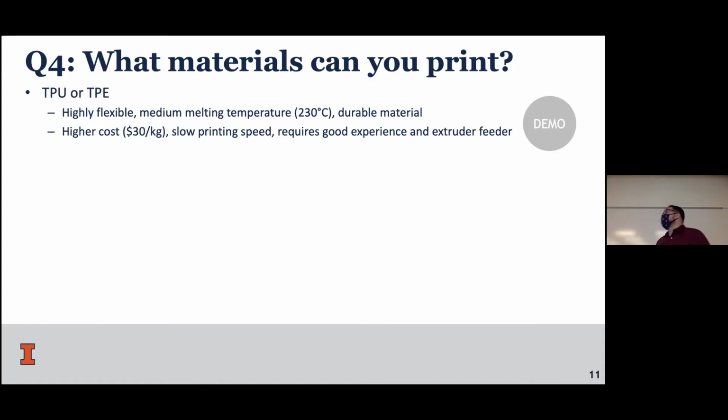Once you've selected a brand, it's usually guaranteeing a certain quality, consistency, homogeneity. But if you really want to buy without looking at the name, you can look at the melting temperature and the density. Usually they give the accuracy of their size. So if you have a printer that doesn't have really good tolerance on filament size, then you might want to change brand for a better filament. So you have to check the size and consistency of your filament. Does it answer? Okay, perfect.